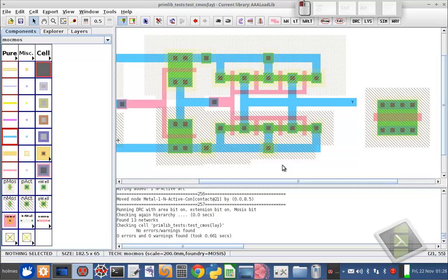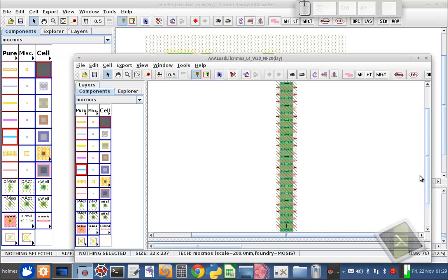And it's generated that transistor design for me in a multi-finger cell. So a lot of the tedious work, if I want to come in here and tie all these together as one gate, I can do that. The general idea is that by using the finger cell and hierarchy, you can accomplish a lot of the scalability aspects of analog design.